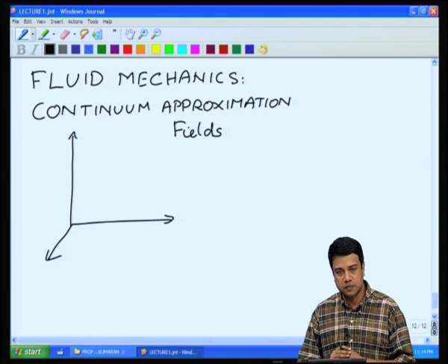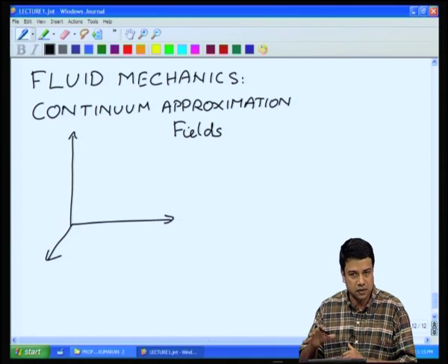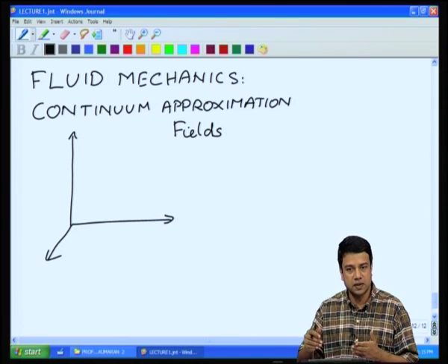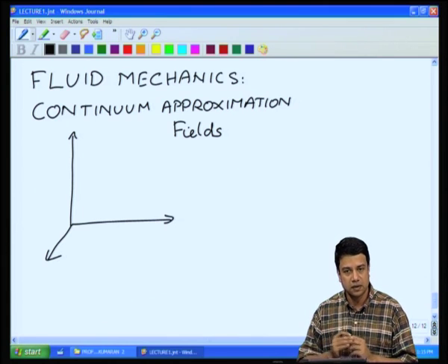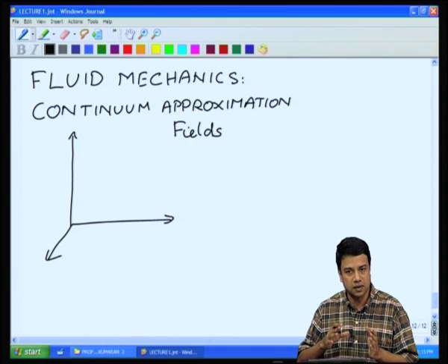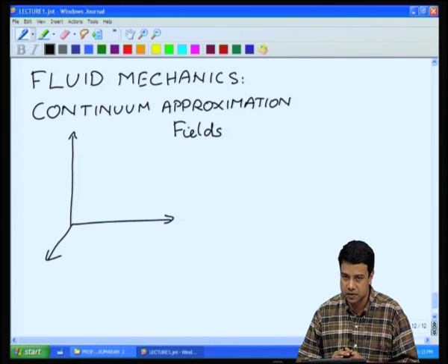The concentration, temperature and velocity fields as continuously varying functions in space and time, and see what constraints are imposed by conservation laws and constitutive relations on how these fields can vary. These constraints give us conservation equations, which are in the form of differential equations, telling you as you go from point to point in space and as you progress in time, how these fields vary. And if you can solve those differential equations, you can get by some kind of an integration procedure the entire velocity field, concentration field or temperature field.